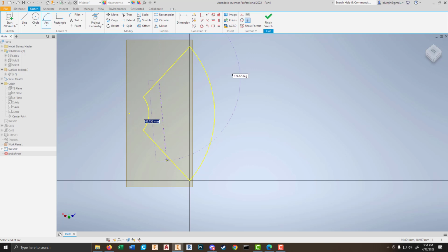And we're going to just do this guy here. All right. Now this arc looks pretty arbitrary. That is because it is. But we're going to give it some constraints again. So we go up to constraints, and we've got this guy here, tangent. And what I really want is to be tangent everywhere. And that is going to be our propeller blade.